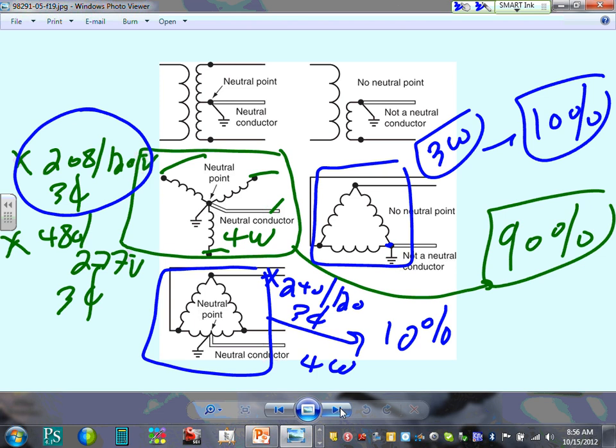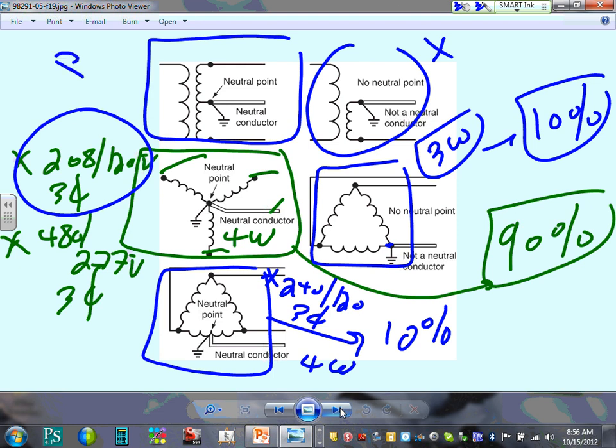We understand this system. So the most important one is the one that I highlighted here. These are the three-phase. These, I've never seen this used. I don't know what the application of it is. This is your residential, right? Residential single phase, 240/120 volt. Okay, we exceeded that one. Can I emphasize, if these are the systems that you start, you always start a power system with a transformer. So this one, the one that we highlighted right in here, is the one that you're going to see 90% of the time.